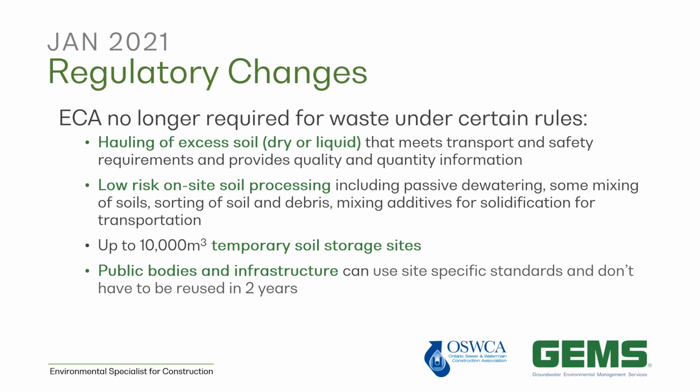Any low-risk on-site soil processing that you're doing, whether it be passive dewatering, mixing of soils, sorting soil and debris, or putting additives in to solidify for transportation, that level of activity does not require an ECA. But again, you're going to want to double check what you're doing as far as mixing soils, because it doesn't cover all mixing. So it's good to have your QP look into that when you have your project scope in place.